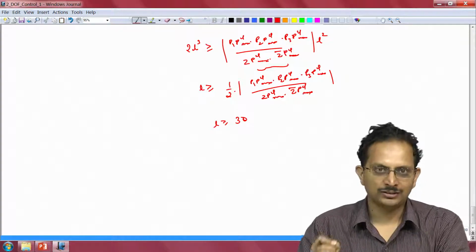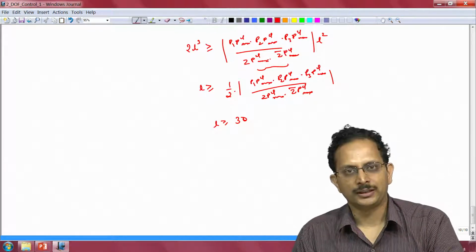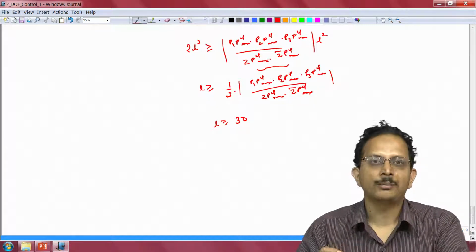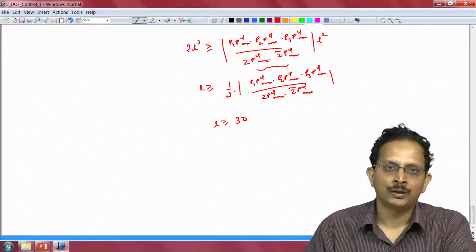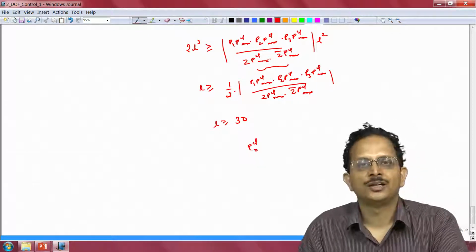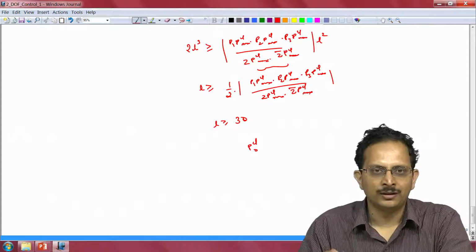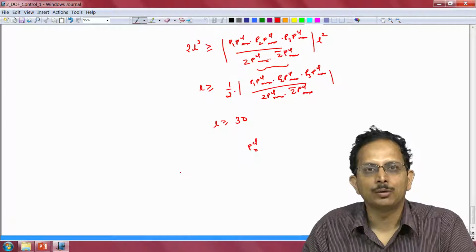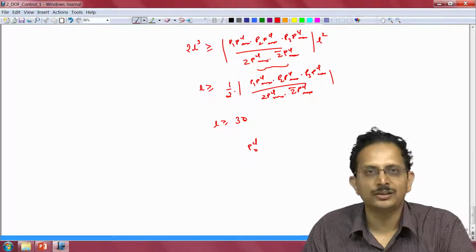So the other step that is remaining as far as the feedback controller is concerned is to determine the gain of that controller. Now since we know that the point PCL0 is a point on the root locus, we can determine the controller gain by once again applying the root locus equation at the point PCL0.